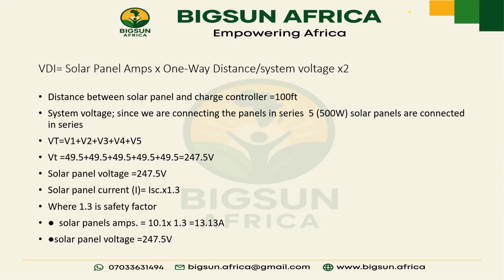So when we punch that in a calculator, we are going to have a total voltage of 247.5 volts. Then the panel current is ISC times 1.3 or 1.2 as the case may be. We know where 1.2 is coming from, right? Or 1.3, the safety factor.